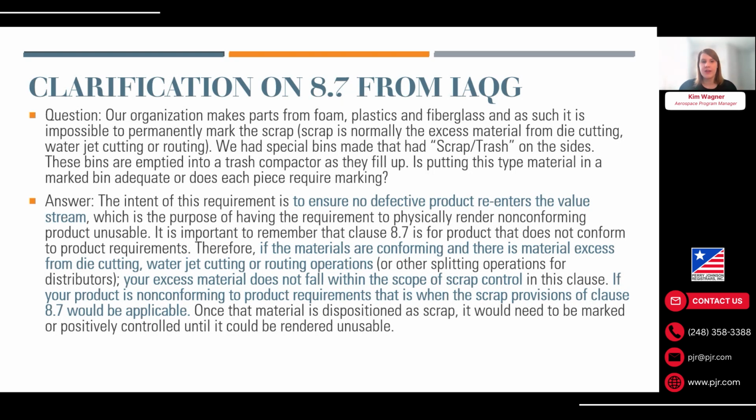So they're clarifying here that the excess material that you deem as scrap does not need to follow this requirement. This requirement is only for product that is non-conforming, and it needs to be rendered physically unusable so no one can mistake it for conforming product. So if we're just talking about excess material scrap, that doesn't fall under that because that cannot be mistaken as conforming product. So it's only after you have a product that maybe failed inspection, that then is dispositioned as scrap, that needs to be positively controlled or conspicuously and permanently marked until it is rendered unusable. So I just wanted to share that in case there was any confusion about that as well.